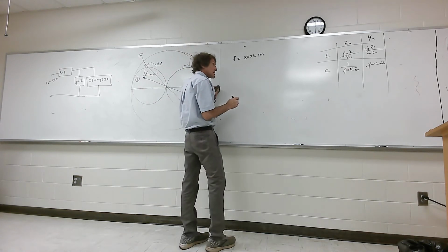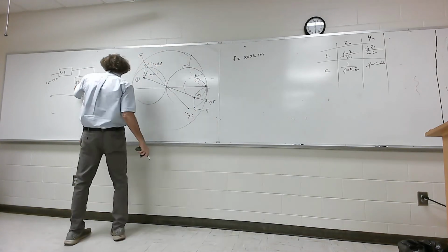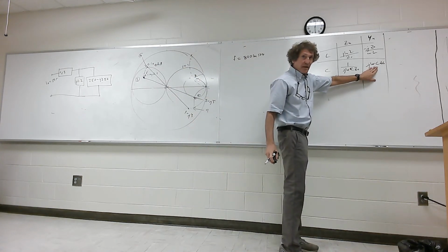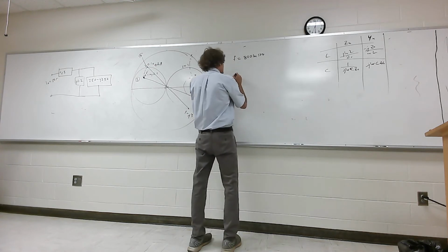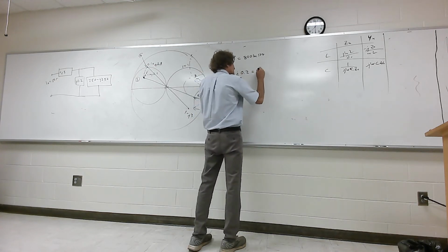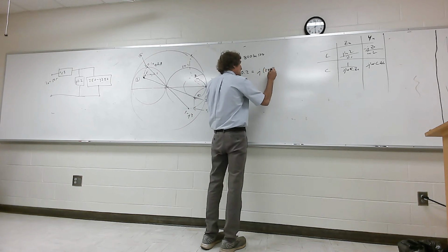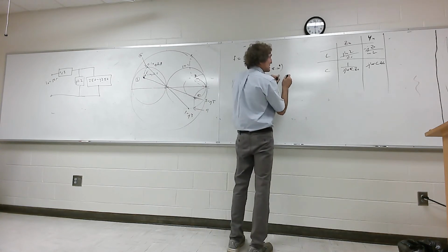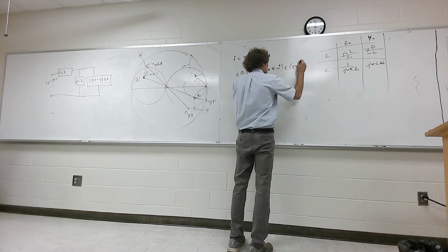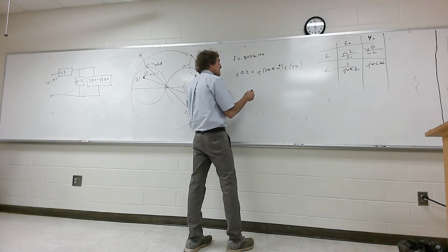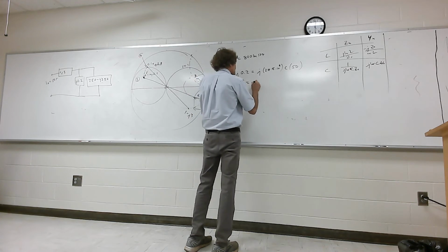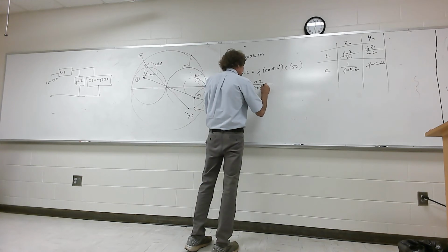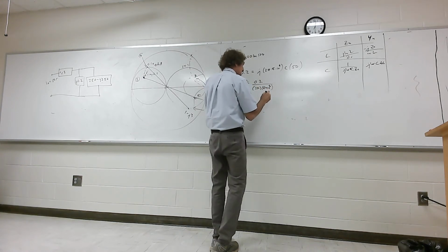Now, when we take a look at this, first element we have to add is an admittance, and we want J0.2. That's the capacitor. Y'all see that? It's a capacitor. That means J0.2 is equal to J omega, so it's 2 pi times 800 megahertz, 8 times 10 to the 8, times C times Z naught, which is 50. I can forget about the J's, and C would be equal to 0.2 over 2 pi times 8 times 10 to the 8,